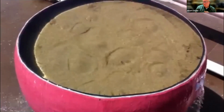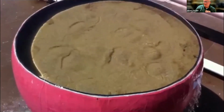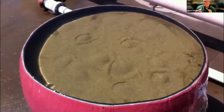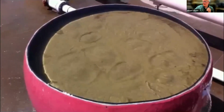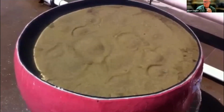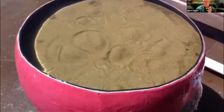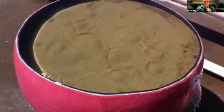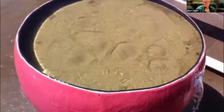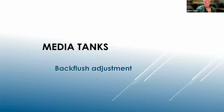So you can see it's boiling there, and it's good and bad. It's good because it's boiling, it's getting the material out. It's bad that it's not uniform over that whole surface area, and that's what we would like to see on these sand media tanks. So within 2 years of us publishing this report and putting videos out like this, they all changed their underdrain designs. And the cost for us to go back and reevaluate is extraordinary, so we didn't go back and check them again. But they all went in there to try to improve the underdrain characteristics here.